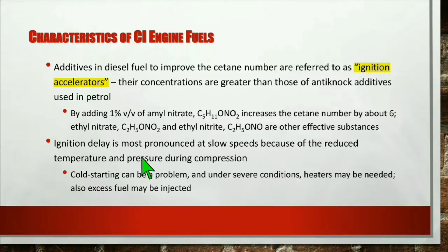Ignition delay is most pronounced at slow speeds because of the reduced temperature and pressure during compression. Cold starting can be a problem, and so can other severe conditions. Heaters may be needed. Also, excess fuel may be injected.